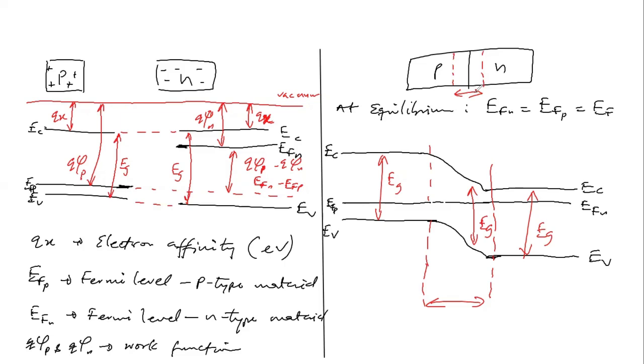So going by this, the depletion region therefore has a net charge, okay? Recall here we have the majority carriers to be holes. So once the holes diffuse into the n-type material, they leave a negative ion, while here we have electrons as the majority carrier. So once they diffuse into the p-type material, they leave a positive ion, right? Okay. So it means that in the depletion region, we have a net charge, okay?